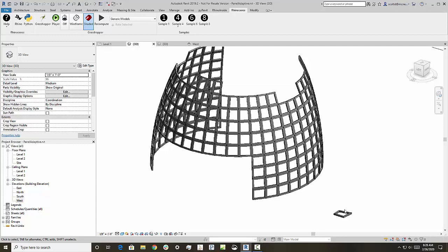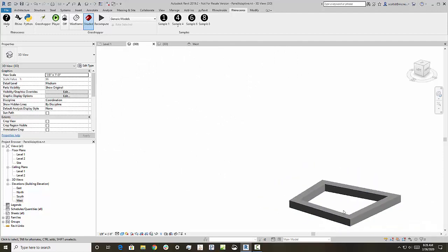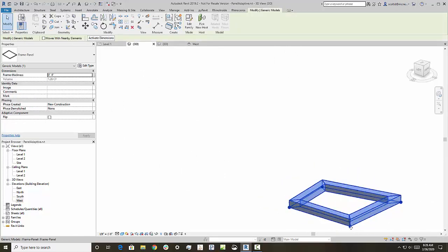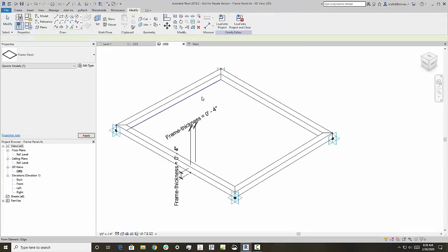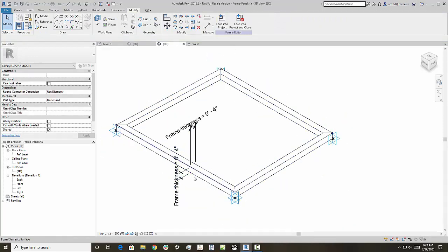that you need a standard everyday adaptive component in Revit, set up with the adaptive component interface. You've got however many points you're going to run. They're all numbered. You also can have parameters in the adaptive component. These can be driven by Grasshopper, by the way. So later in the process, if you want to change this, that's allowed. You can even, obviously, change it per adaptive component if needed.